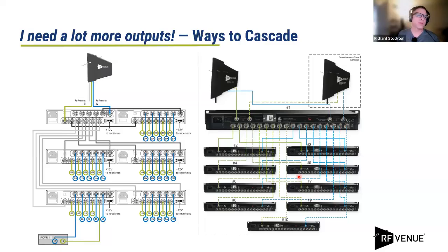Yeah, the message here is with all the different distros you can get, you definitely want to maximize your system for the number of channels you need, but then also leave room for growth. So when you're buying a primary and secondary distro, keep that in mind, and try to leave some output ports open for more receivers, and definitely a spectrum analyzer such as our spectrum recorder and our RF Explorer, where you can take a direct output of your antenna rig to analyze.